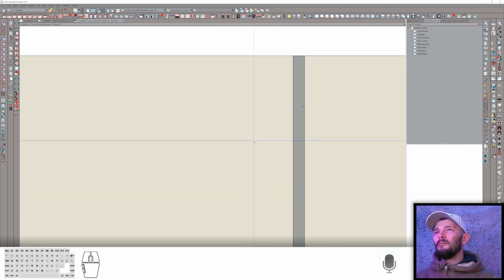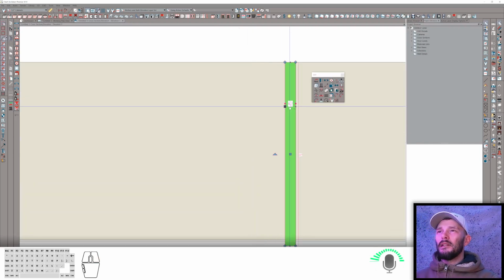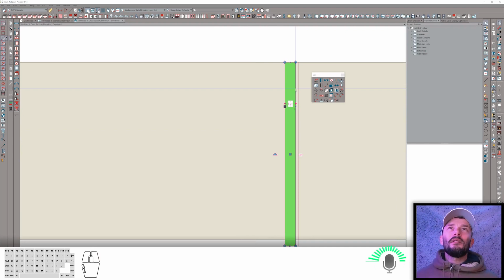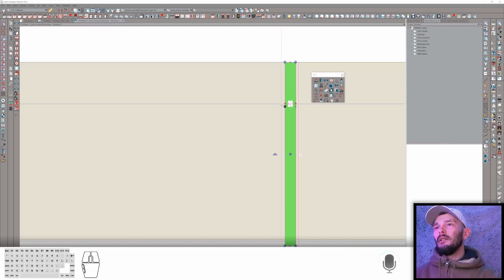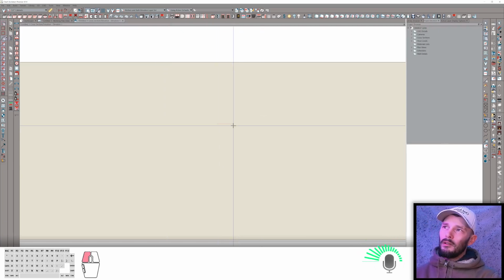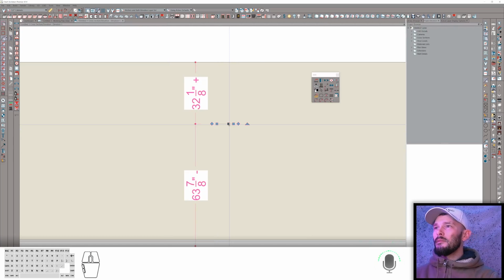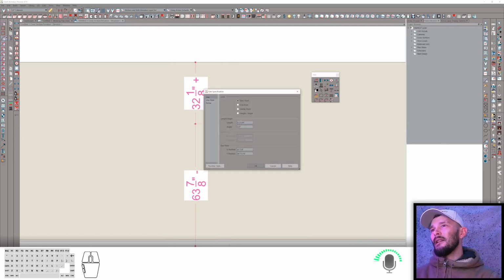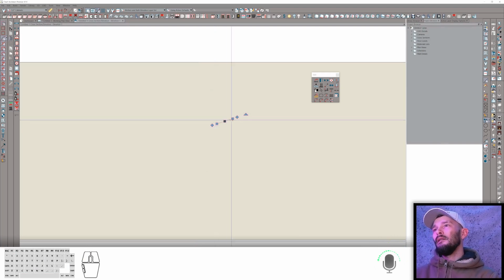All right. So let's rotate this. And here's the problem with this. What is the problem with this? You'd have to make one for every slope that you might need. So really, I don't even want to start with a solid because I want to start with a line instead. So I want to draw out a line, and then I want to spec that this line has an angle of 4 and 12.